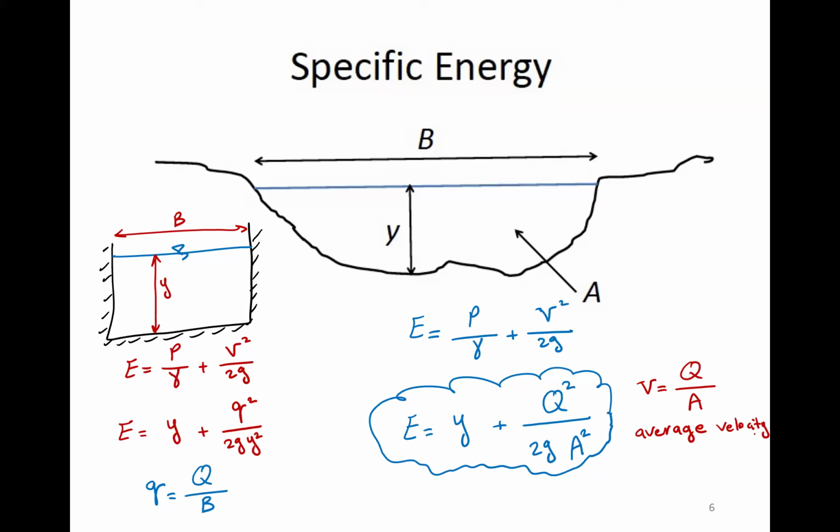So in our equation, we're not going to change anything. We're going to say, okay, we're using an average velocity, but actual velocity may not be just the average discharge divided by area. So how do we take that into account? We do that by a simple approach: let's not change the equations, but add a correction factor. Let's add an alpha here and call this alpha parameter the velocity correction coefficient.